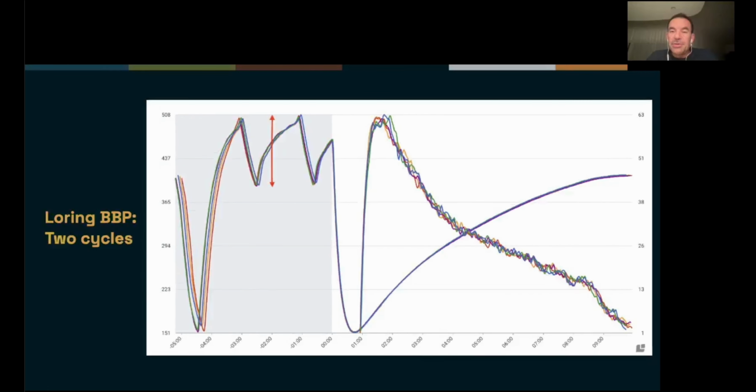It'll save you a little bit of time. But some people use much tighter min-max settings and bounce between them many more times before charging. That's fine. I'm generally pretty comfortable with setting them about 50 degrees Celsius apart and running it to the maximum twice, minimum twice, and then charging on the rise.